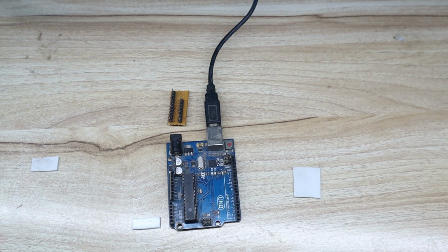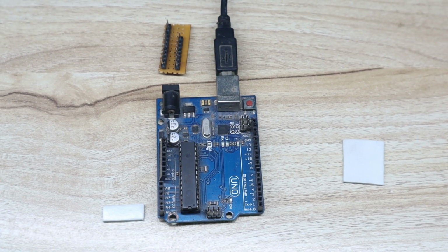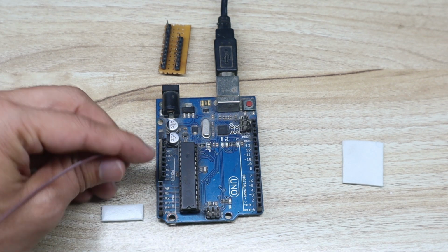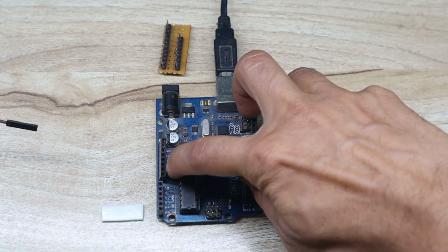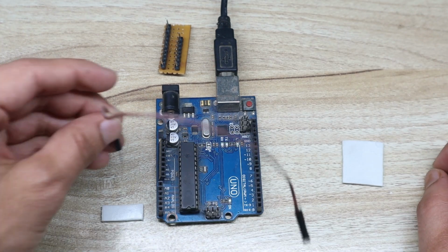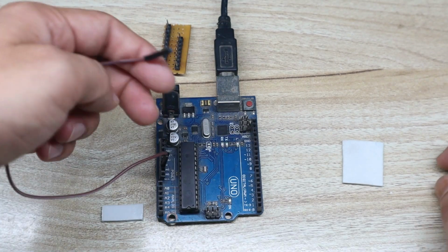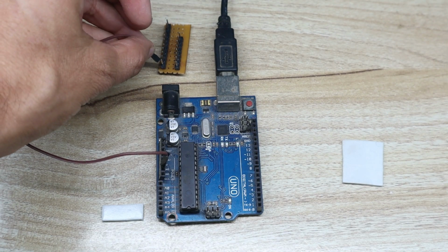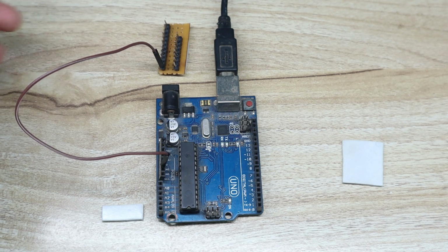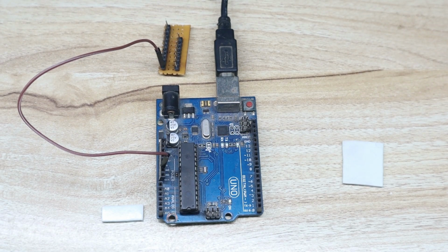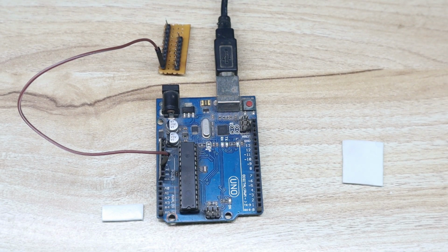So first, you should connect the common ground pin from the Arduino. This is the ground pin. Easily you can find the ground pin name on the Arduino. You can take any ground pin and just connect it to the common point. So later whenever we need a ground pin, we can take it from here, okay? Then after that, the next circuit is the I2C LCD.